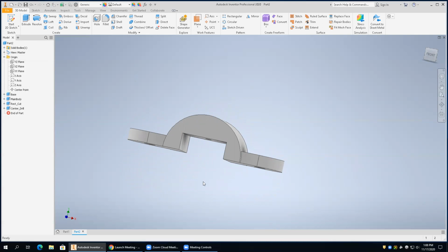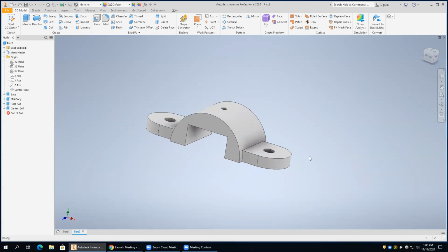All right, so let's go ahead. We'll change that back. We're going to go back to the rectangular cut, show dimension, double click that, make that 1 unit, and then you can just do your local update, and we're good. What the author is trying to show you is the cool thing about this: you have the ability to make those changes, especially the way they're linked, parent, child, parent, child, parent, child.